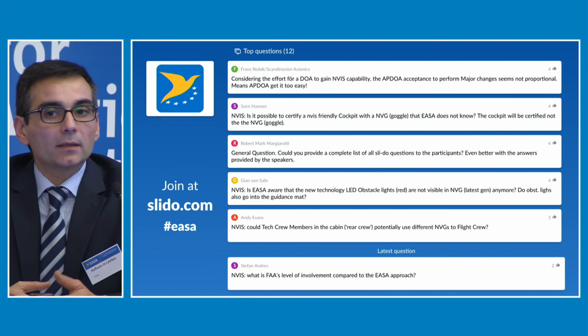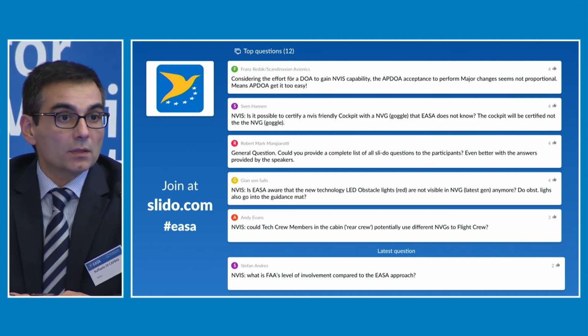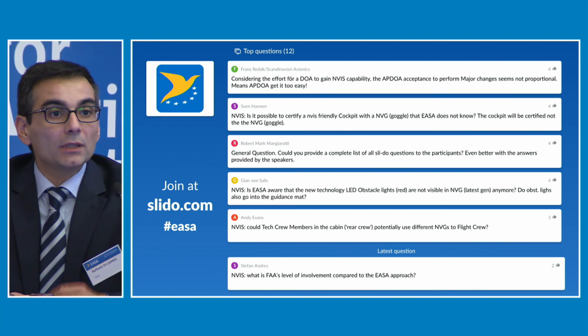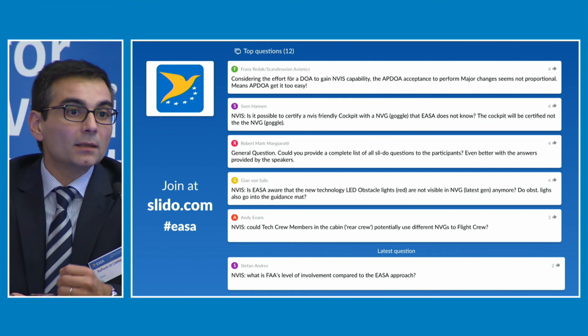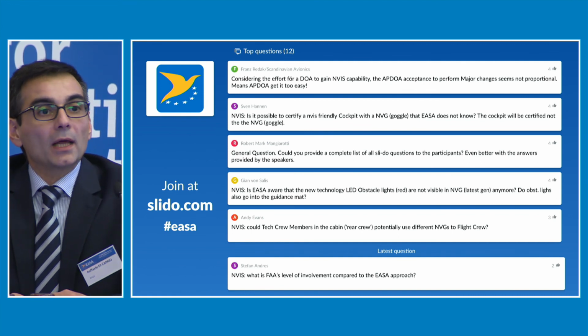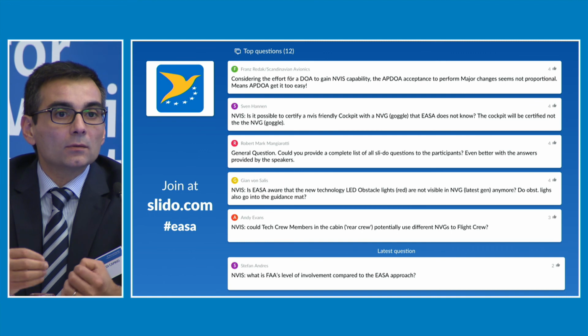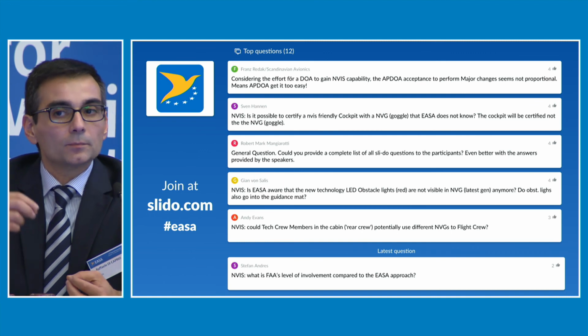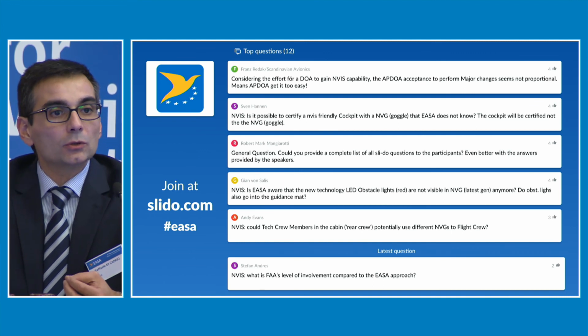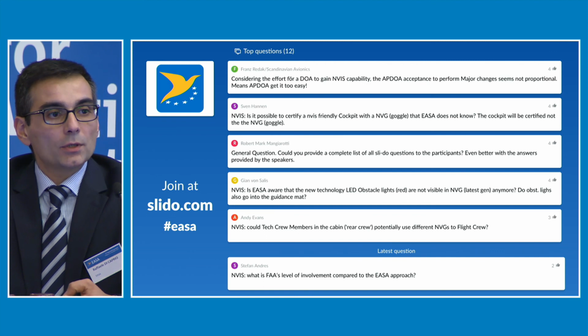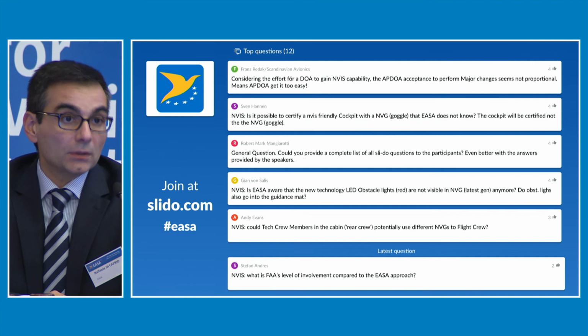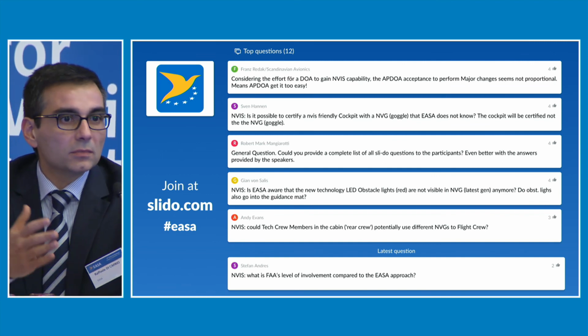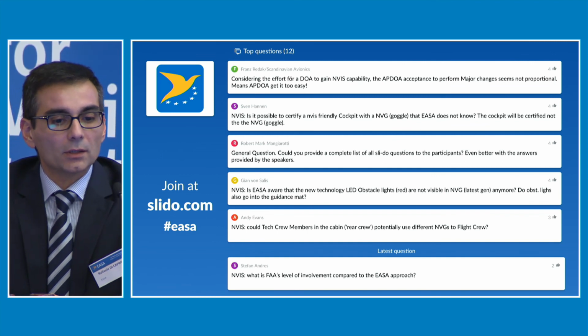And by that meaning that if you read carefully the MG16, it doesn't say that you have to be ETSO approved, but that you have to be ETSO compliant. That meaning that you can demonstrate by yourself compliance to the DO-275 requirements, which is the minimum operating performance specification of the TSO C164. I think that's the correct number.